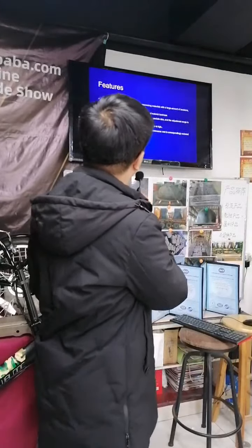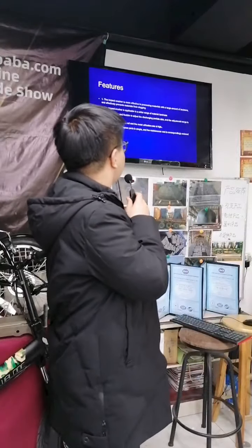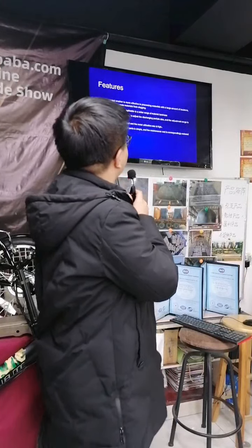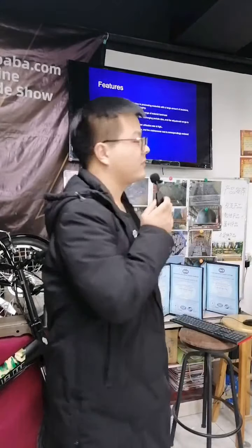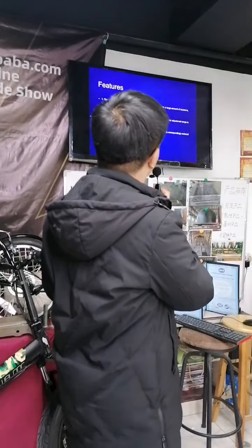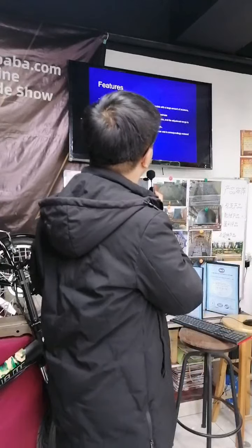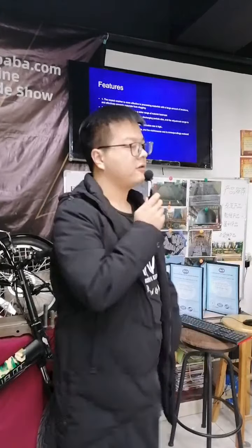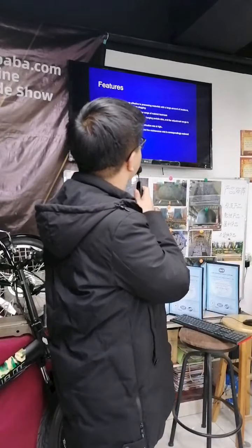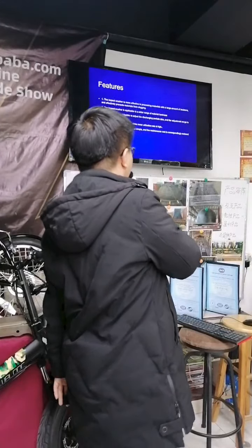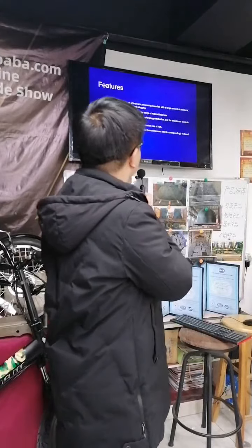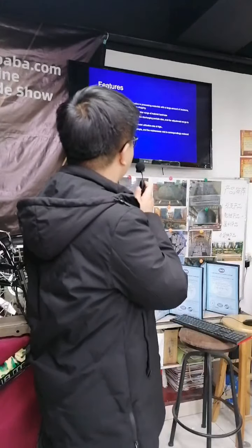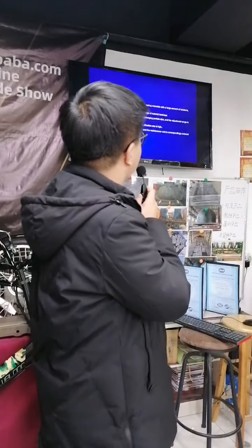The features of this kind of crusher: it is more effective in processing materials with a large amount of moisture and effectively prevents materials from clogging. The impact crusher is capable of handling a wide range of materials. It is convenient and flexible to adjust the discharging particle size, and the adjustment range is wide. The wearing parts are small and the weight is high. The replacement of spare parts is simple, and the maintenance cost is reduced.